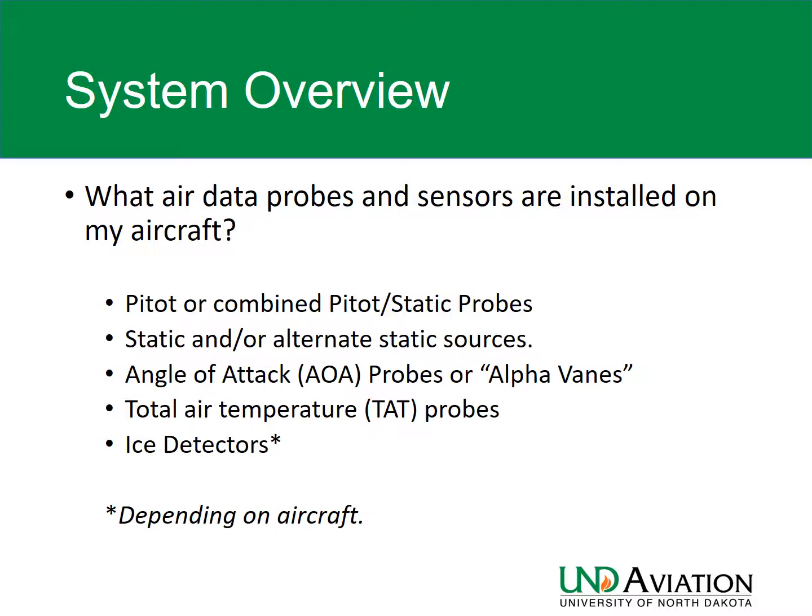And then in some cases they're more advanced, and they'll use a sort of a vibration which determines, if there's ice accretion which is occurring, the vibration frequency will change and then signal an alert that ice is accumulating on the aircraft. And that actually does occur on the CRJ aircraft. So that's something we'll see in later content. So there's a variety of different sources and probes, and there's oftentimes redundant probes on the aircraft.